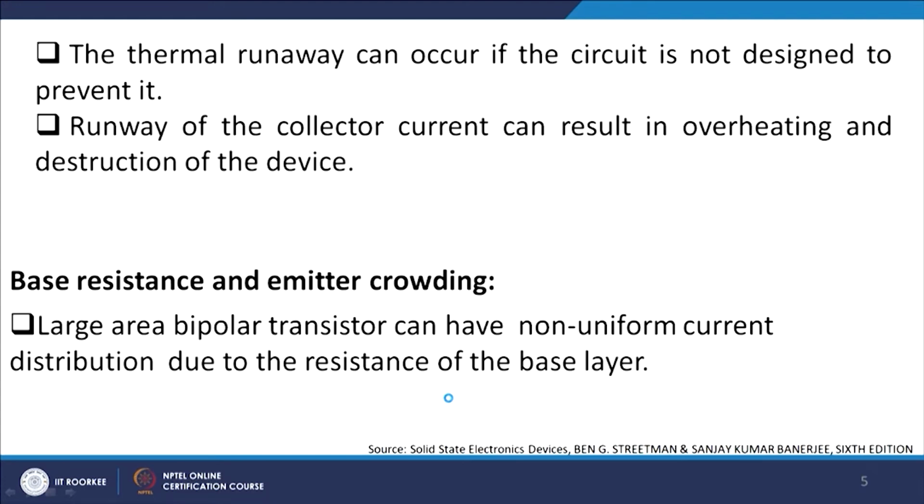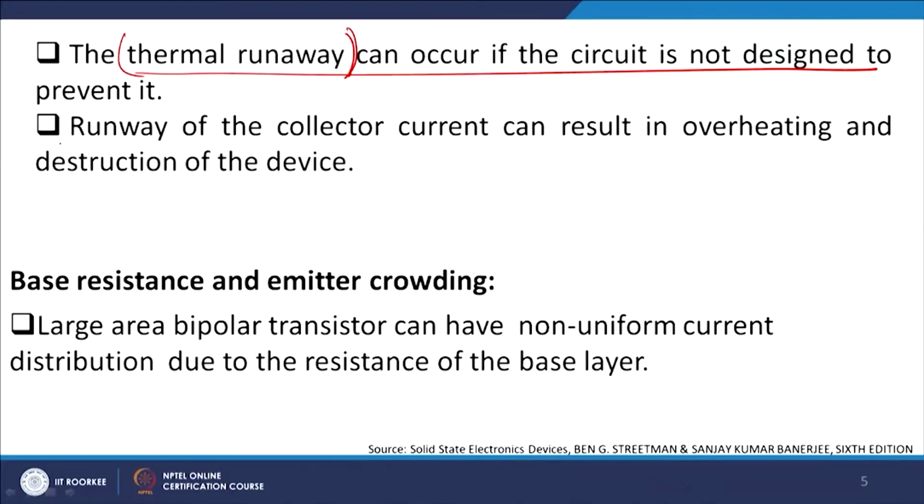Now, thermal runaway is a standard problem area, and if the circuit is not designed properly, you will have a thermal runaway which will make the device non functional and will burn up within a very short period of time. As I discussed with you, runaway of the collector current can be due to overheating and the destruction of the device, and this is what leads to final destruction.